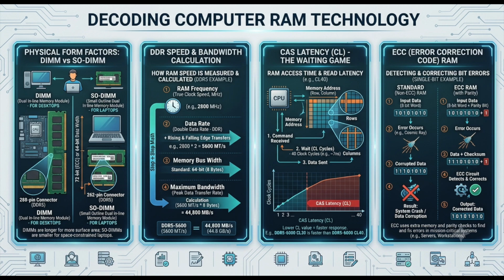So here's where it gets really interesting, especially for you listening, because solving this bottleneck completely changes how you should be buying and upgrading your devices. It really does. If that single physical pathway between the memory and the CPU is completely maxed out, how do we get more data across the motherboard? You utilize multi-channel memory architecture. Dual channel, triple channel, or even quad channel.